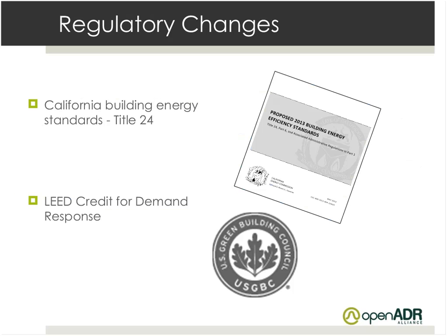A couple other things worth mentioning. California's Energy Code, Title 24, has a reference to OpenADR in the code that takes effect in 2014. In my interpretation of the code, newly constructed buildings over 10,000 square feet will require a DR interface based on an industry standard, of which OpenADR is the leading standard. So we will see quite a strong pull-through of OpenADR deployments in California, and this also will bring in core manufacturers that will ease the deployment of OpenADR through programs in the rest of the country.